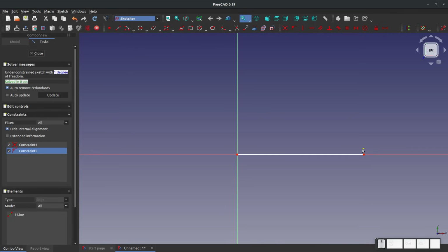This little guy right here means coincident. Being coincident means that it is fixed upon this line. In other words, one point is fixed upon something else. That's what coincident means. So, for example, if I draw a point, then I can choose the coincident relation, and I can choose this point to be fixed upon this plane, right? And now it is fixed, coincident.